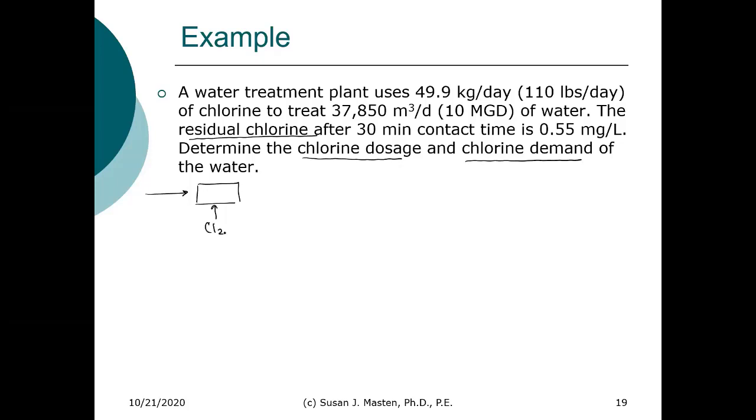We add chlorine or hypochlorite at some dosage. We have a distribution system. We want to ensure that we have a chlorine residual in the distribution system.